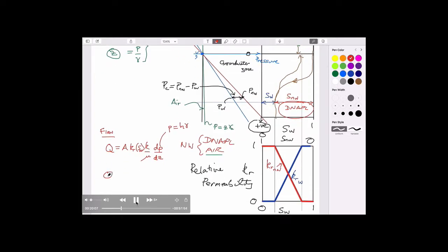If you haven't looked at it already, last Thursday's presentation was about some different ways of being able to characterize this term, relative permeability, as a function of saturation in a very practical sense related to the gradation of soils. So finer gradation soils and coarser gradation soils will have characteristically different relative permeability and capillary pressure curves, and we can define those. So that's basically what last session's discussion was, to top off this idea of the fact that we can look at these two fundamental characteristics.